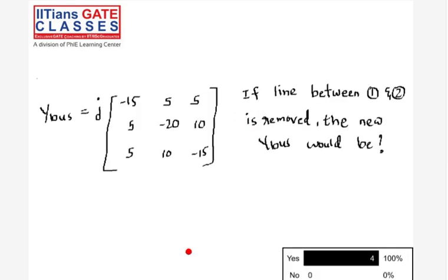Before we go on to the next topic, just wanted to let you know. The question that you should have asked me is that we have the option of representing a network by either its impedance or admittance. Why do we choose to represent it by admittance? That is because, as we saw, Ybus is extremely sparse. There are a lot of sparsity techniques in matrix representation.